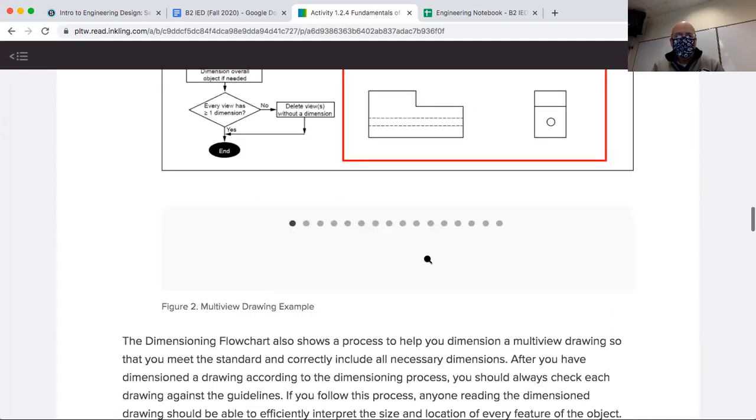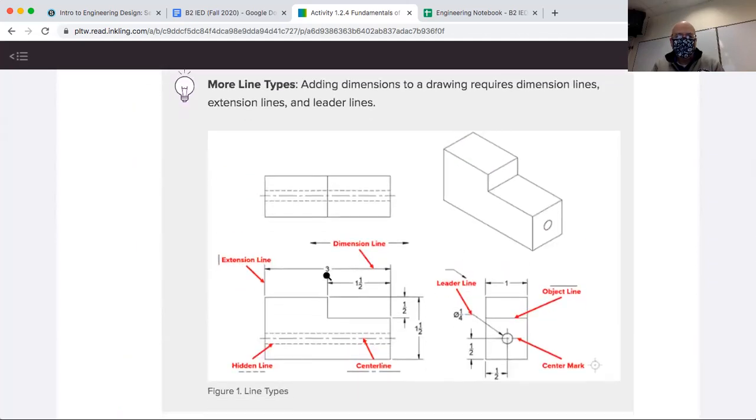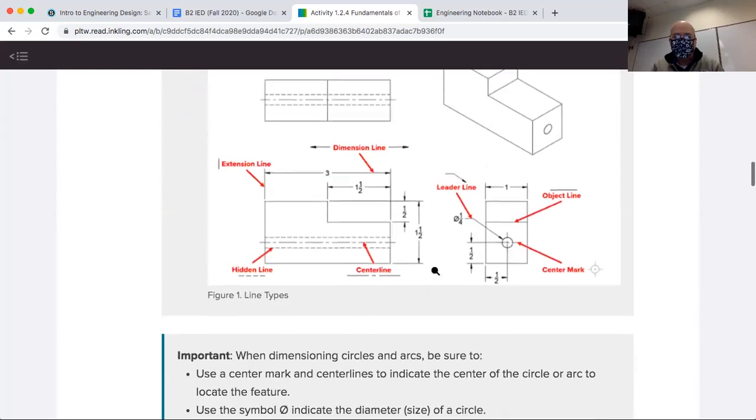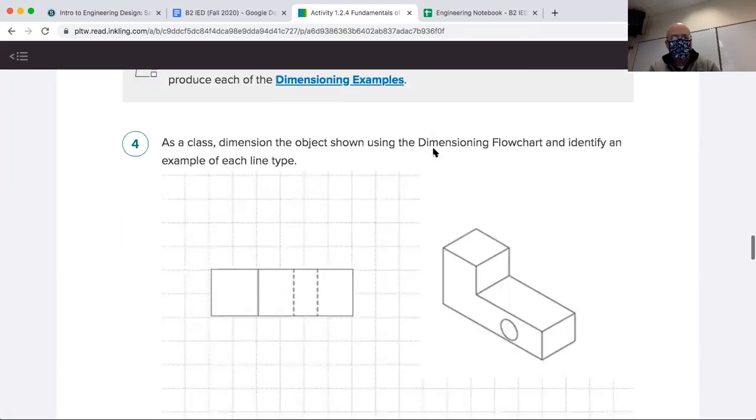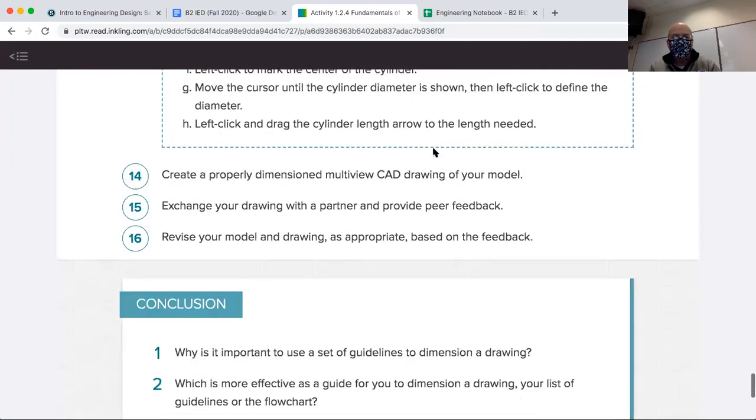That's okay. Something else I forgot to tell you is that this 3 and this 1.5 and that half and that 1.5 and all those others, those are inches. Inches is the standard unit in engineering. Inches or feet, depending. And so that's why you don't see units. Again, they don't want clutter on these drawings. They just want to give you the information as quickly and efficiently as possible without a lot of mess. People have to read these drawings and figure out what they mean.